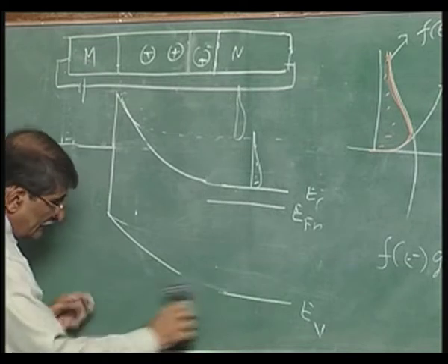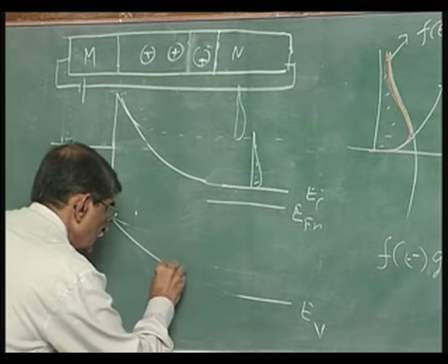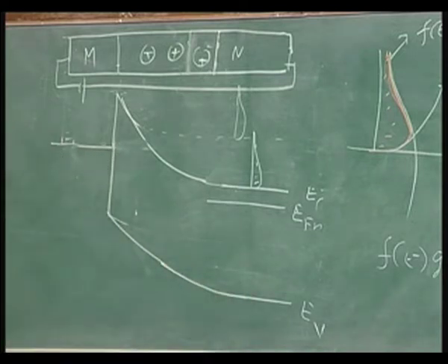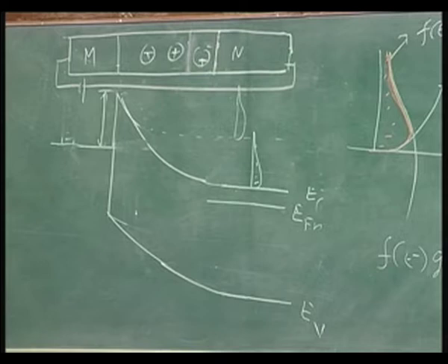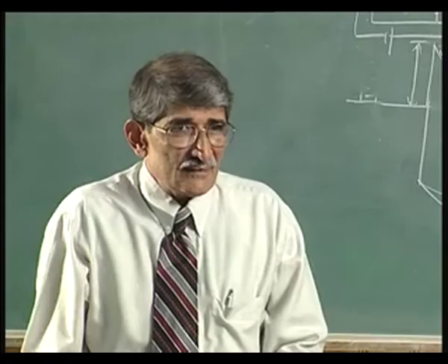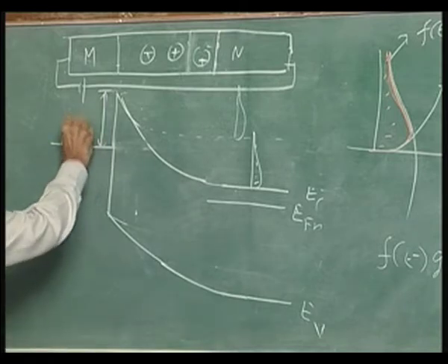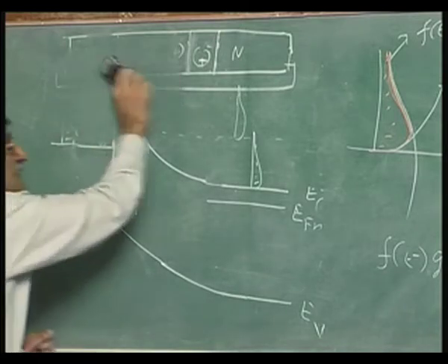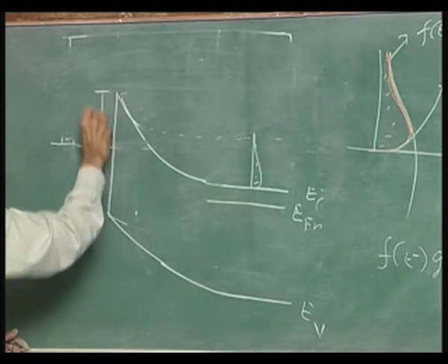So, that is the new energy band diagram. What is the consequence of that? These are just basic concepts, which once clear, we can move further. What happened to this barrier? That barrier has not changed, because there is no depletion layer there. There is no potential drop across that. So that barrier remained the same. Phi Bn does not change. So now let me just draw this here. Once again, whatever you have got there, this Phi Bn has remained the same.